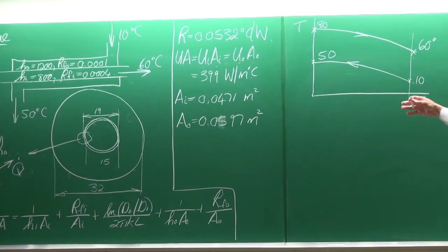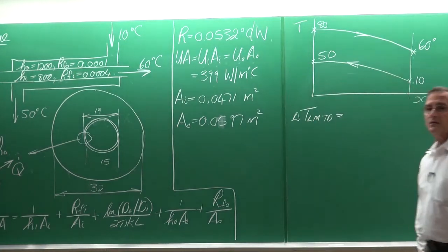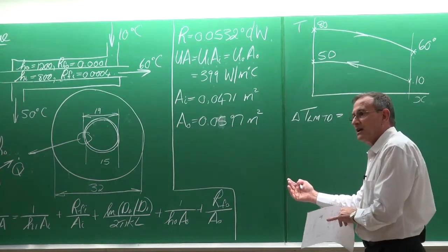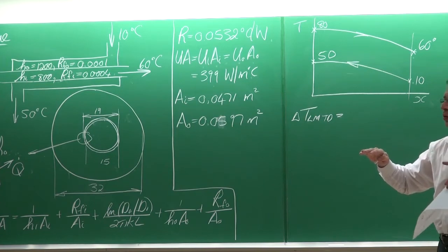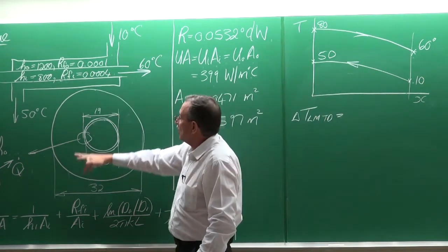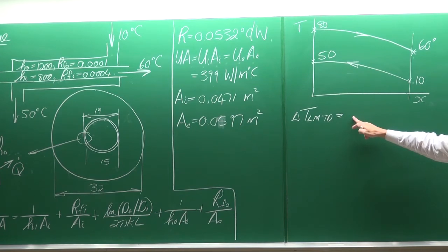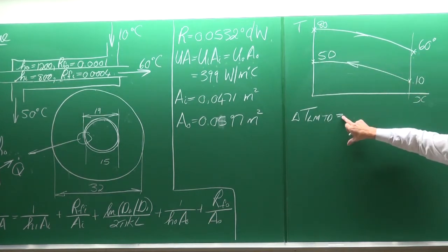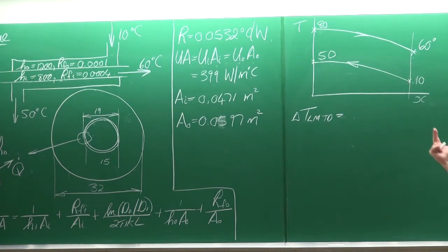Okay. So with that temperature distribution, we can calculate the LMTD. And in heat exchangers, I've discussed it to you at the beginning of this lecture, what is different from this chapter than other chapters, typically the chapter that you did on internal forced convection, where you could have a wall with a constant heat flux or a wall with a constant wall temperature, is that in this case you've got two different streams separated by the wall. And the general guideline is you can always use LMTD, except if you're going to end up in the situation where that temperature and that temperature is the same, then this is not going to work. You'll not be able to calculate the LMTD, but then you can just take that temperature as the temperature difference.